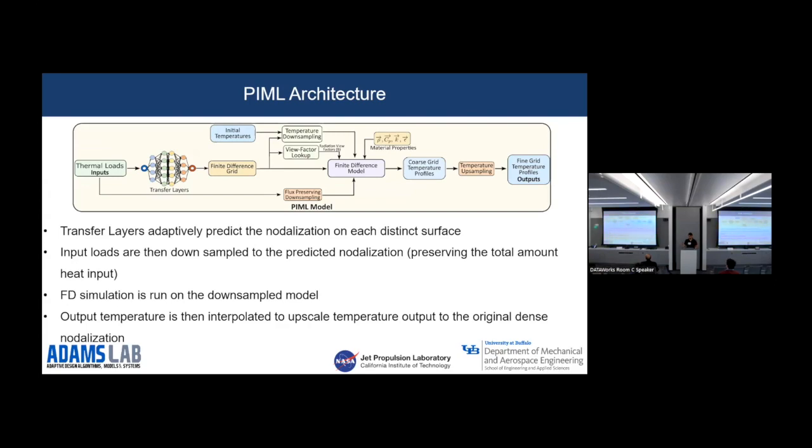You could say, okay, well, that's extra work as well, but let's assume those are given to you. And now we're asking the model to give me a new mesh specific to that loading environment, right? So note the distinction between this paradigm and the last slide, where the engineering team only gets to pick one model, in practical terms. This time around, we can have a different nodalization for every single loading scenario.